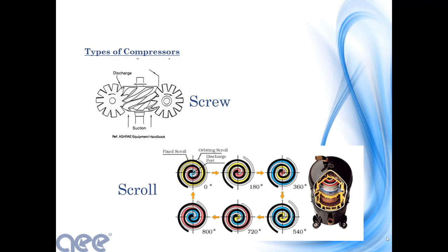The next step up was the scroll chiller. These are relatively new. I think they've been around probably 12 to 15 years. With scroll technology, these are actual physical scrolls, one inside another. This black scroll is inside of what's now a white scroll, and the refrigerant is what you see in yellow. When the scrolls rotate within each other, you can see the chambers compress from a large volume to a low volume. The refrigerant comes in one side, gets compressed, and comes out the other side.